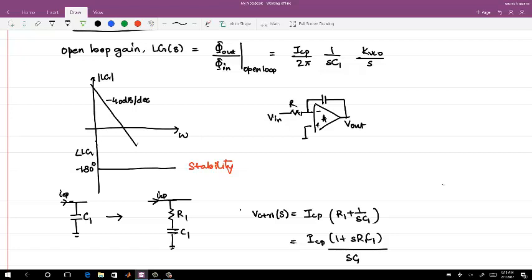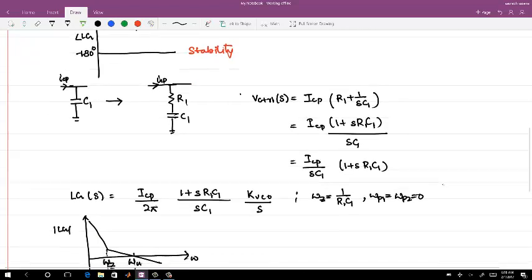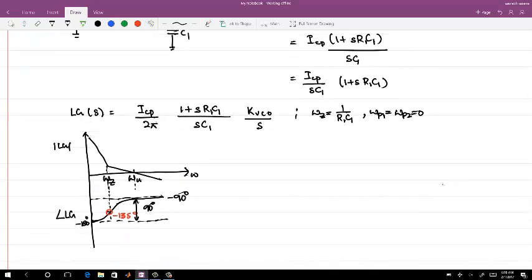All those things depend on your noise characteristics in this PLL. So we will see what should be the actual location of omega z, but that will be decided by the noise. It depends on what unity gain frequency you want, that is, what bandwidth of the PLL you want, and the phase margin also. But it is easy to achieve a 90 degree phase margin in this one.